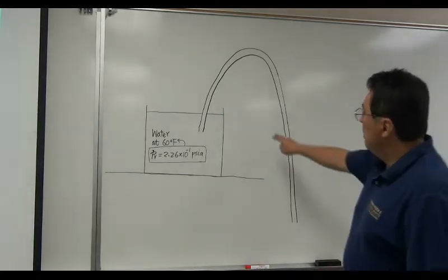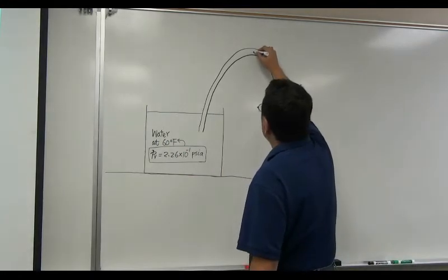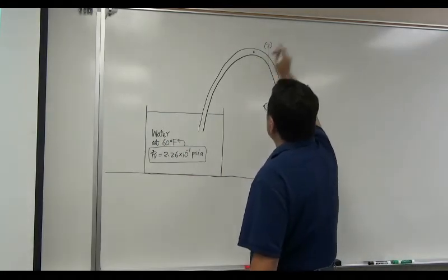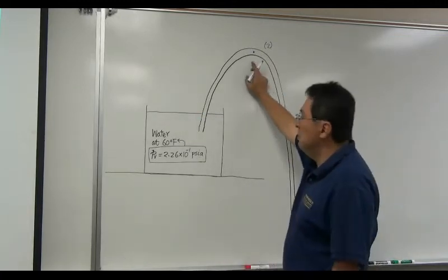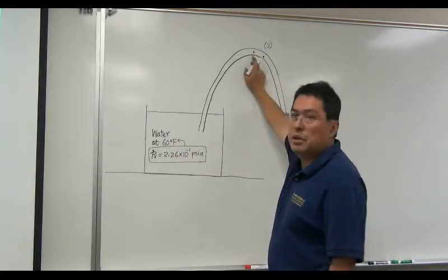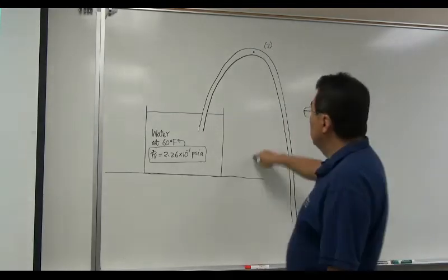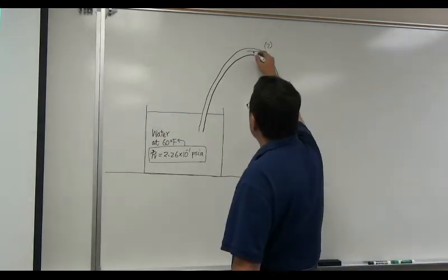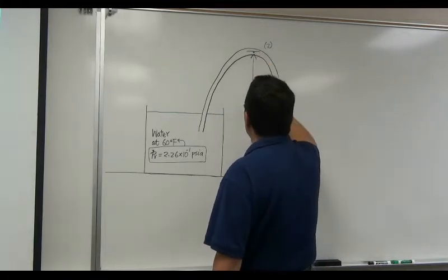So the condition of that is right here, 0.2. This is the lowest pressure throughout this siphon. If the pressure here becomes this pressure, whoa, we are going to develop cavitation. Okay? So that actually determines maximum height of H right here without having cavitation.